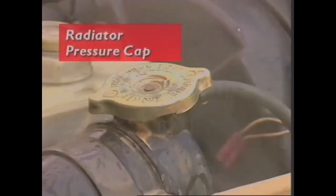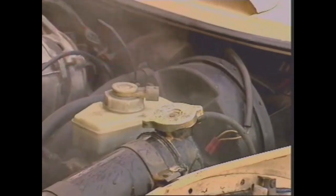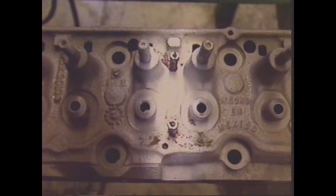If a coolant boils, it can be as serious for an engine as having it freeze. Boiling coolant in the water jacket becomes a vapour. No liquid is left in contact with the cylinder walls or head. Heat transfer by conduction stops. Heat builds up, and that can cause serious damage.